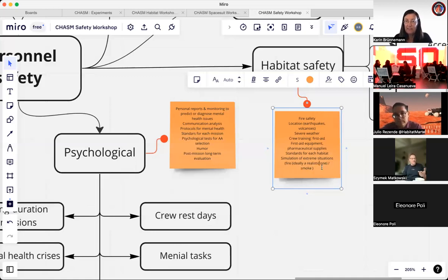What do people do when they wake up and they have to run for their lives? It all goes to the pre-evacuation time, which gives you the time between encountering the fire and being safe. And the shorter the time is, the better, of course. This is also part of a risk assessment, and procedures for what to do.